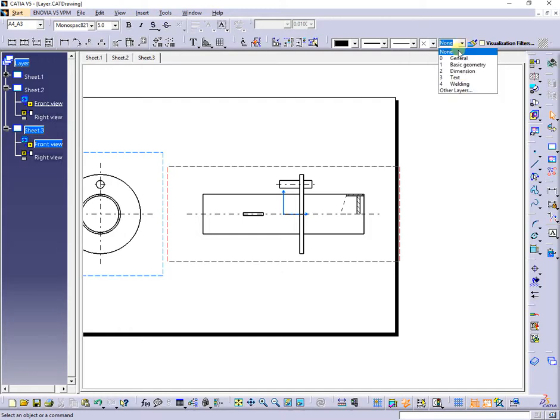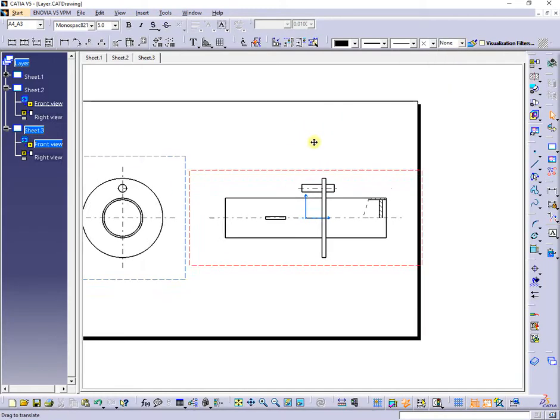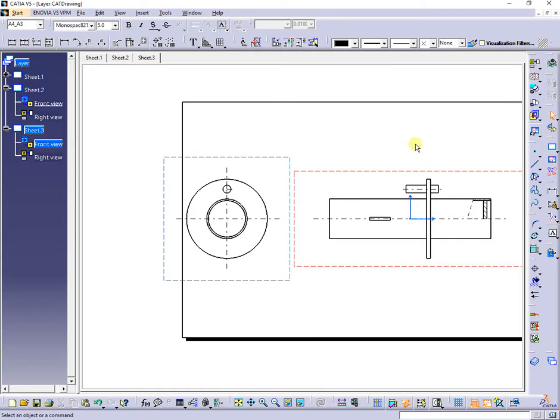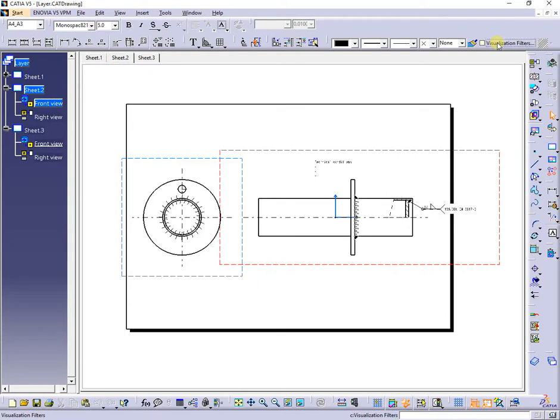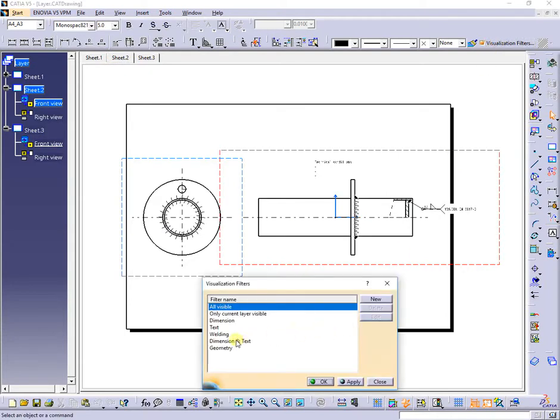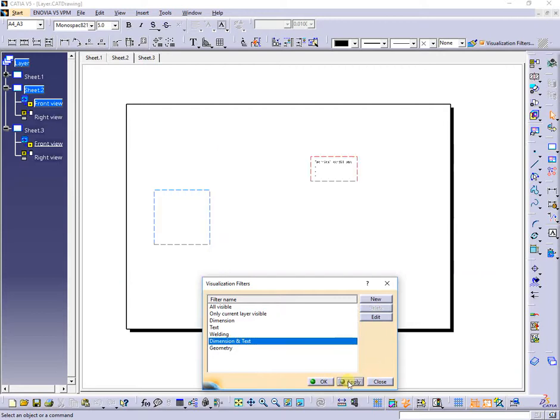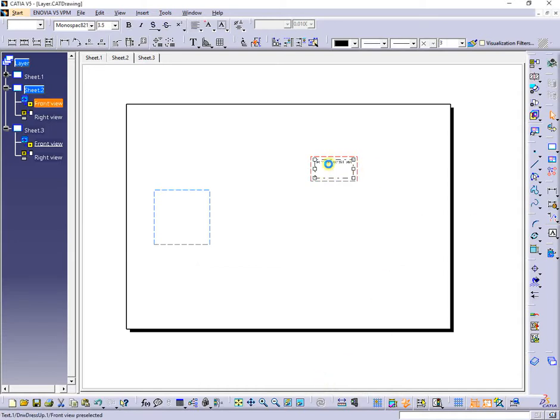The same procedure can be used in the case of copying data between two different drawings. In this case the data will be copied, even if the second drawing hasn't all the layers defined. Also, the copied layers will not be shown in the Graphic Properties toolbar drop-down menu, but if we click on the features then the layer number will be shown.